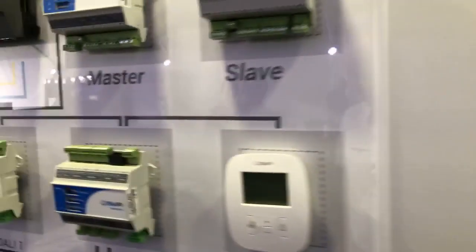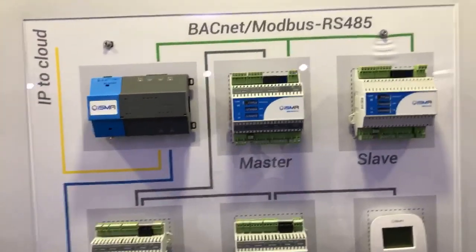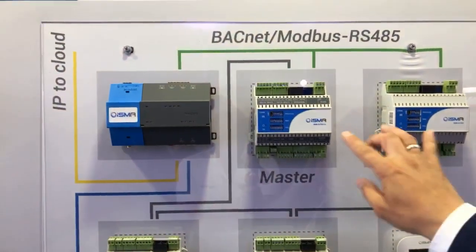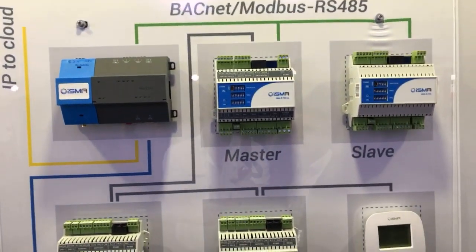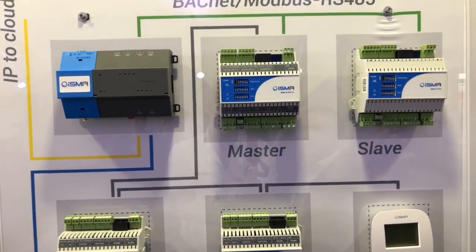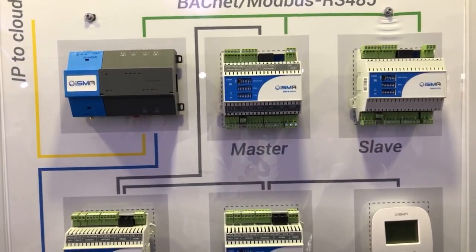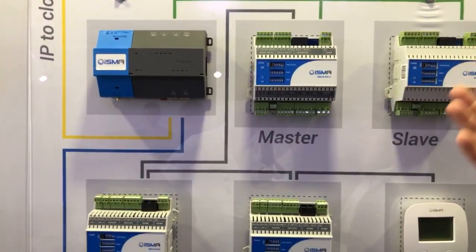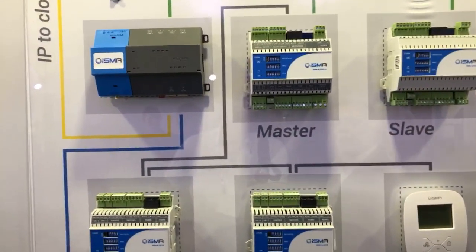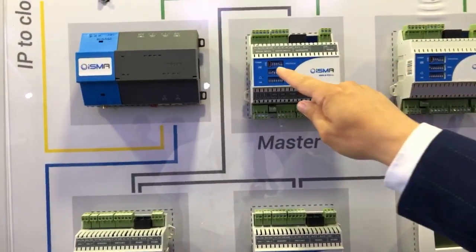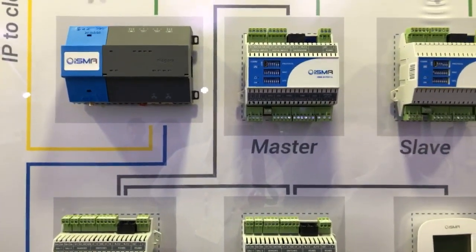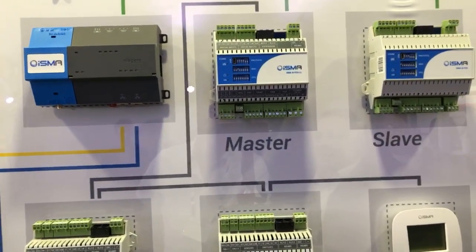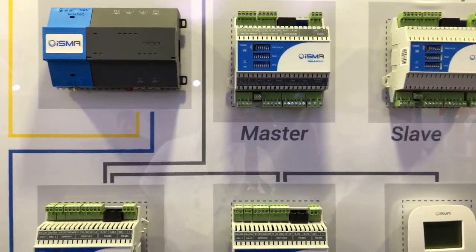On the left hand side we've got the J6000, the OEM, the J1000. These two are RS-485 controllers dedicated for fan coil units with a preloaded application, and they are powered by Sedona. So it's very powerful. Whoever knows Sedona is familiar. We can change the application through the USB, so you can connect a little laptop and change the application. But it comes from the factory with the preloaded application.